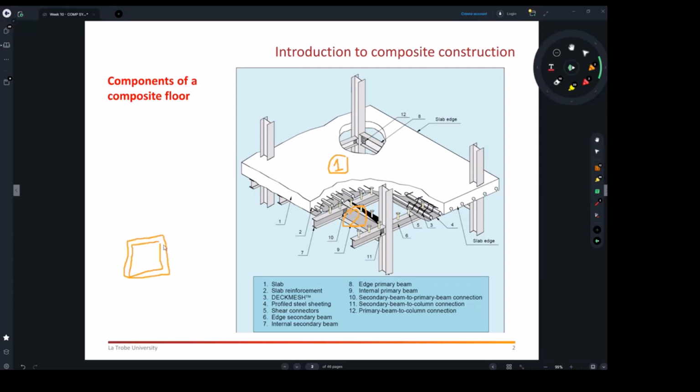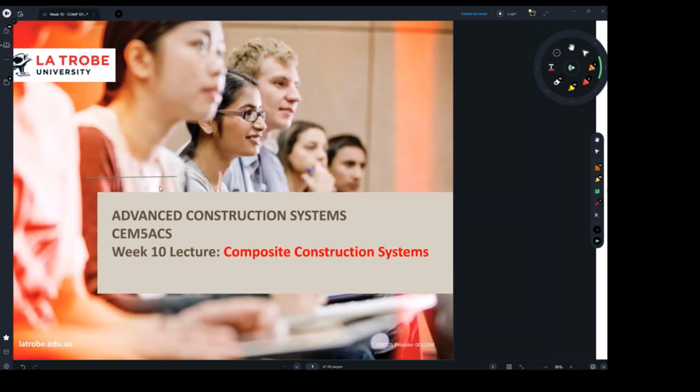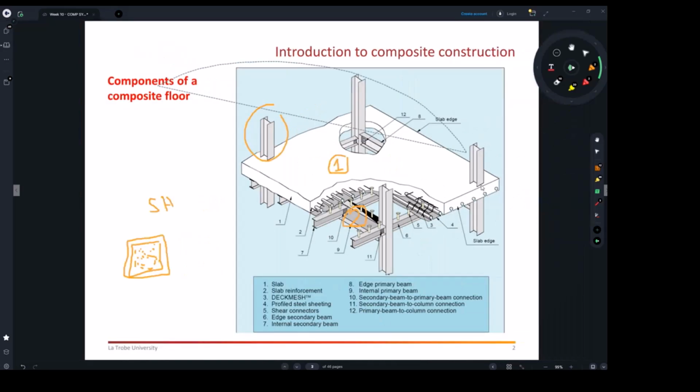It's like you have a hollow section column, like a square hollow section, SHS, and then we fill the inside with concrete, and that will give us very well improved capacity. So again, we've got a hollow section. We still can do composite with these sections, but you need to do a formula. So we will talk about composite columns at the end of the notes.